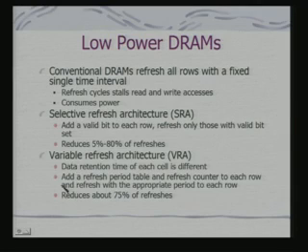So, what you are talking about is the refresh cycles with respect to each row, and it reduces about 75% of refreshes. Obviously, this increases the on-chip hardware, but what is the advantage? The advantage is that your major power consumption is in the refresh cycle, which is in a sense unnecessary consumption, although it is for retaining the data, but not related to the computation. Fine. So, you try to minimize the energy consumption there.